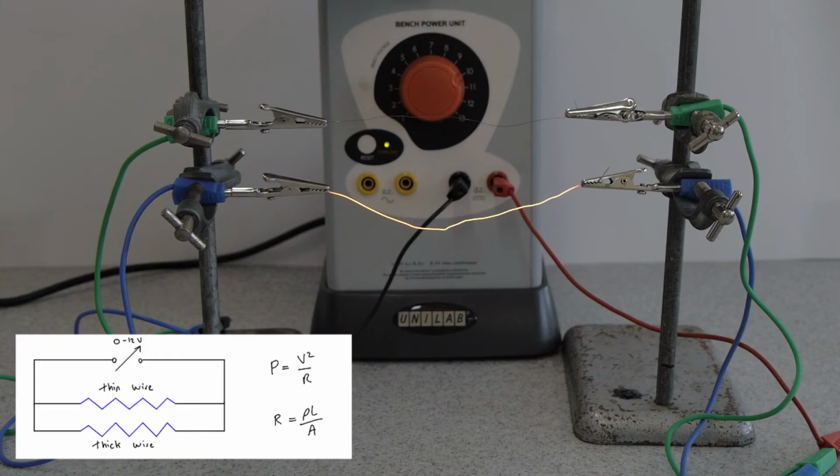However, the thicker wire, if they're both the same length and made from the same material, will actually have less resistance. Remember, R equals rho L over A. Both wires here are made from the same material, therefore they have the same resistivity, and they have the same length. Rho and L are the same for each wire, but A, the cross-sectional area, is larger for the wire on the bottom. If we divide by a larger value of A, we will get a smaller value of R. Less resistance for the wire at the bottom. Go back to P equals V squared over R. V squared is the same, R is smaller. Divide V squared by a smaller number, you will get a larger power. So more power is being dissipated in the wire on the bottom.